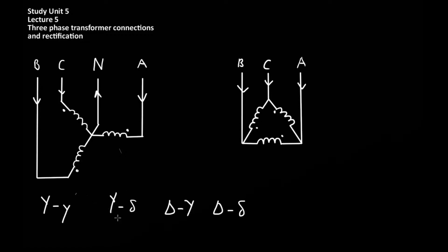Delta-Y configurations are useful for step-down voltage applications. The delta-delta configuration finds application in medium-high voltage applications where no neutral terminal is required. Last but not least, Y-delta configurations are used in step-up applications.